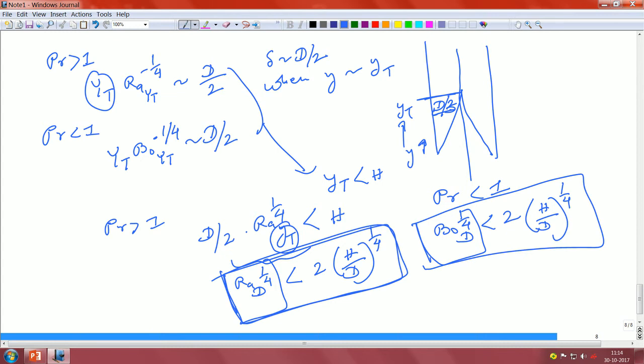If the Rayleigh number exceeds the order of magnitude predicted by this expression, then of course you are not going to have any such flow. The assumptions on which you have based your velocity and your Nusselt number expression are all going to break down.